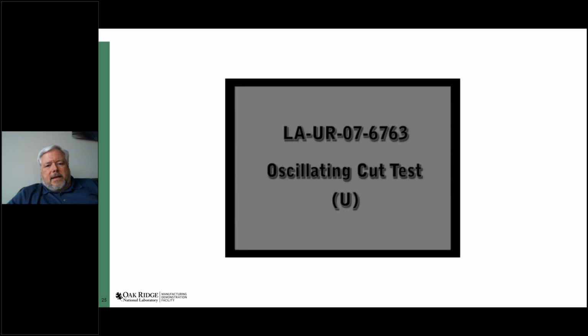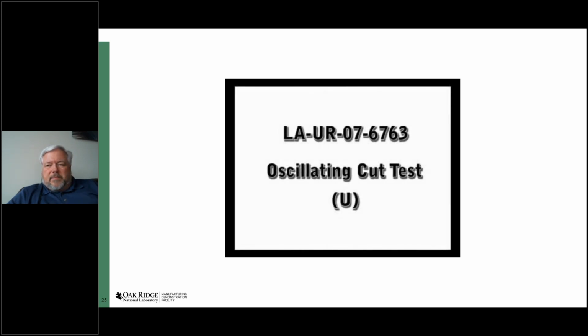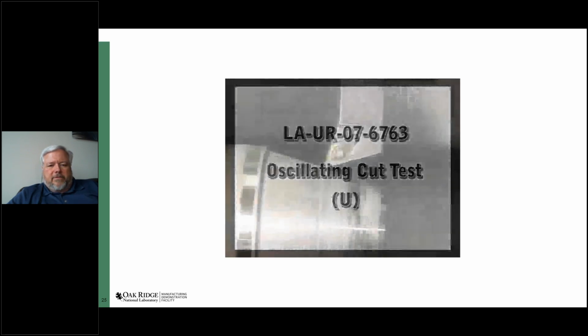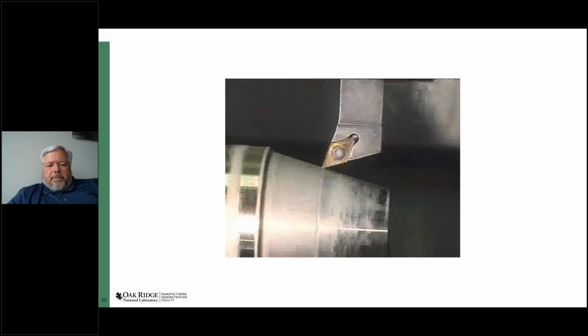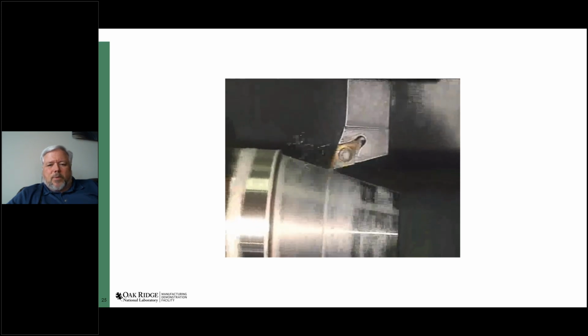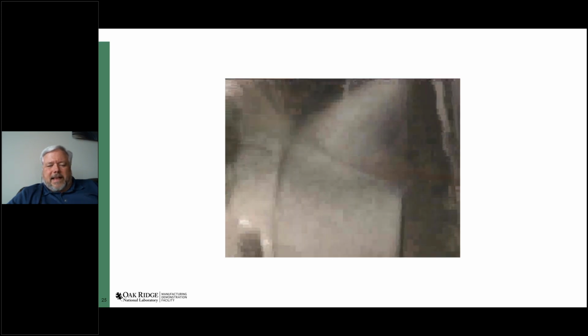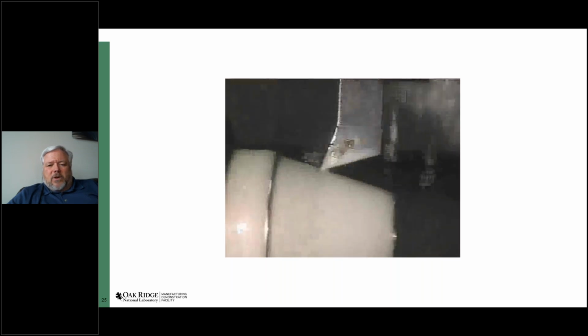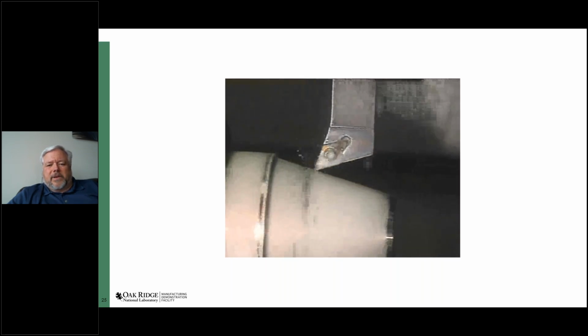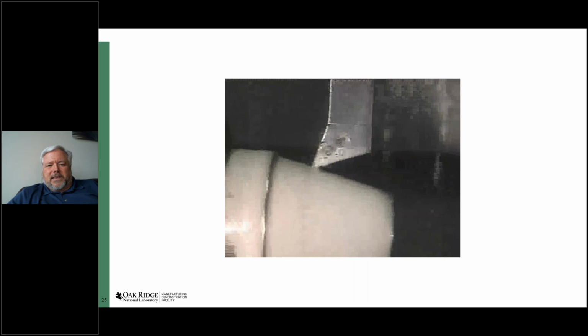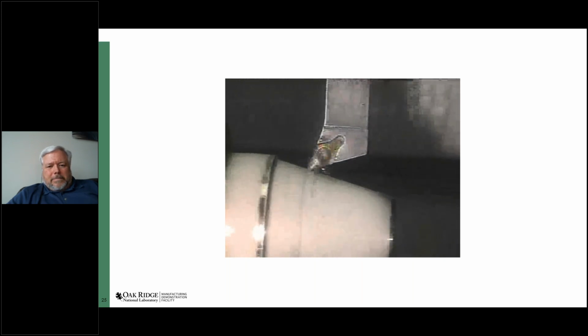Okay, I'll show you one more. This one is kind of entertaining, you might enjoy it. This is a material that the heat of the cutting is enough to make it catch on fire. And so breaking the chips was really important in this case. When they form a big snarl, that's bad. And so here are a few pictures that show the snarl forming.